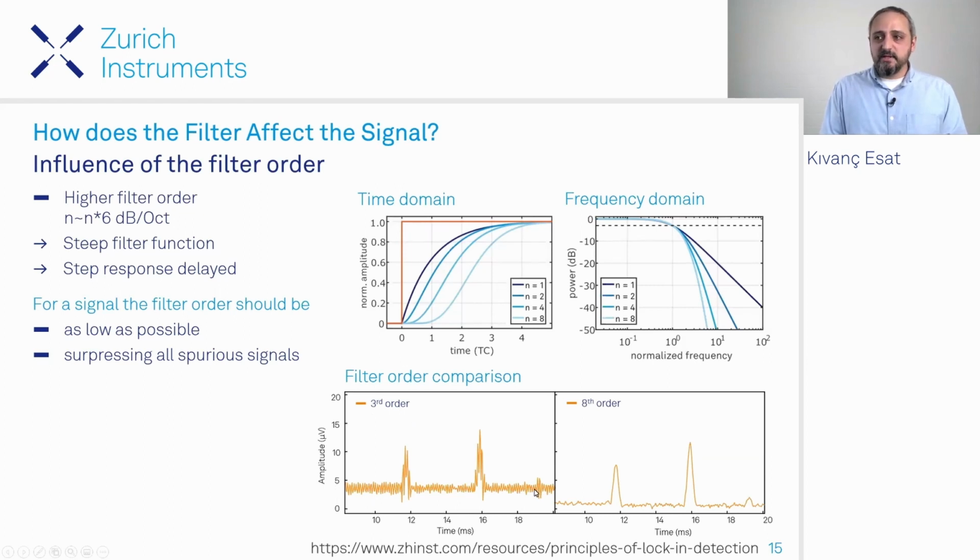How it reflects itself in a signal: here we have a third order filter, we see the features, but there's an additional modulation on top. This order filter cannot clean this up. To solve this problem, we can increase the order here, and you see the features are there. We even capture a feature that we couldn't resolve before.